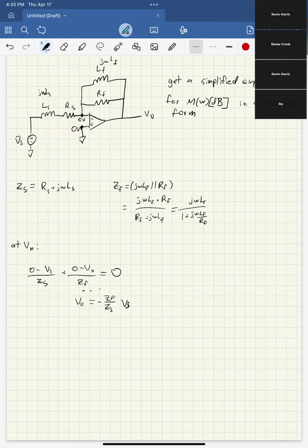On to the question, I was a little bit confused about this last week. Are we trying to convert the formula into a different form in terms of dB? I'm not exactly sure what it will be on the quiz, but when it asks for a magnitude question, it's saying first find H of omega, then turn it into the magnitude of H of omega, and then turn that into decibel form. It's all the same thing, just thinking about it in different ways. Those are the steps.